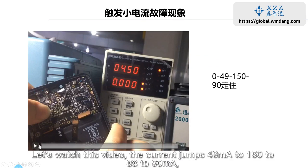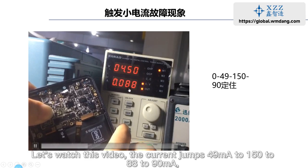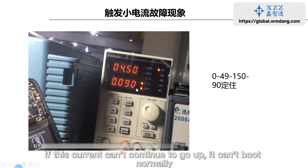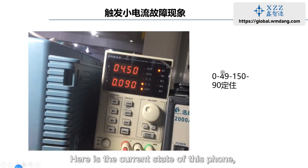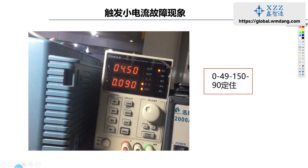Let's watch this video. The current jumps from 49 milliamperes to 150, to 88, to 90 milliamperes, and then the current doesn't move. If this current can't continue to go up, it can't boot normally. Here is the current state of this phone. It jumps from 0 milliamperes to 49, to 150, to 90 milliamperes. It cannot be turned on normally.